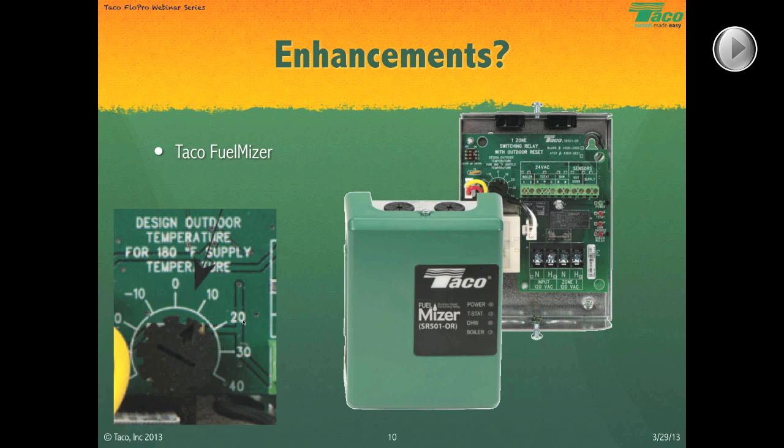Just a slight word of warning. A lot of guys will look at this and say, well, I want to be safe. I don't want the phone call in the middle of the night saying this control isn't giving me hot enough water. So instead of setting it to 0, I'm going to set it at -10 because I want to have enough. And that sounds intuitive, but it's actually counterintuitive. You've just gone backwards. If I set that dial at 0, that's telling the control at 0 degrees outside, I want 180-degree water in the boiler. If in hopes of getting extra, I set it to -10, I've done completely the opposite of what I want. Now I'm telling the boiler at -10 I want 180-degree water.